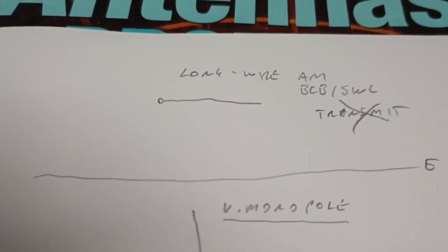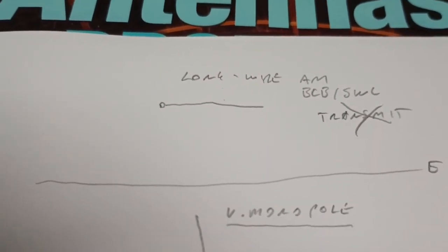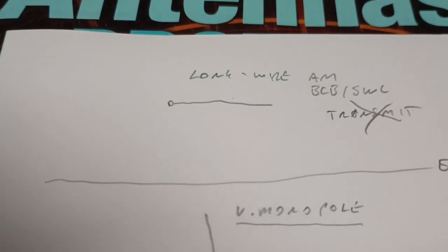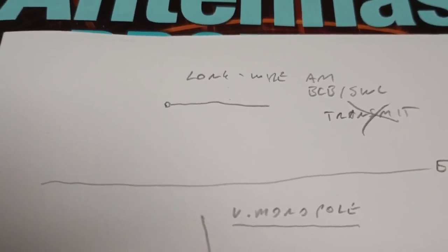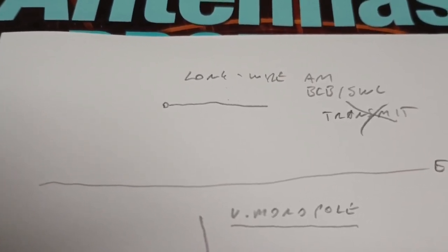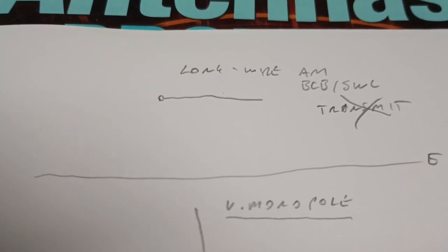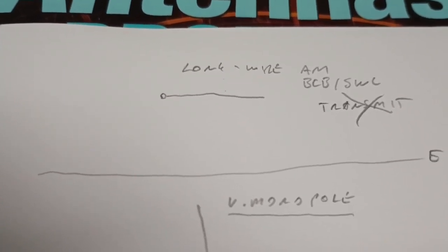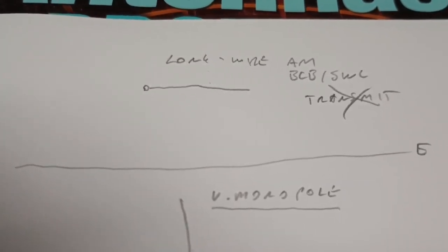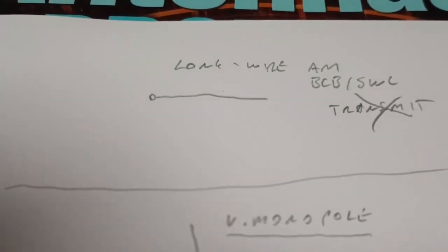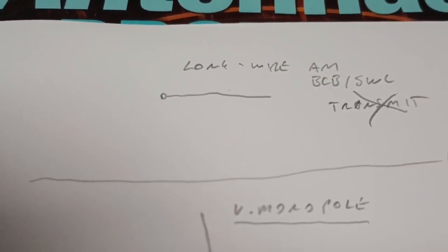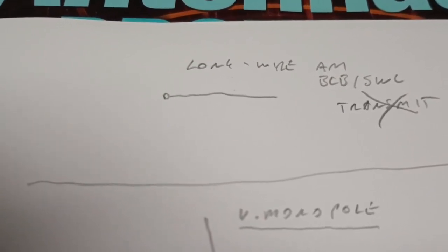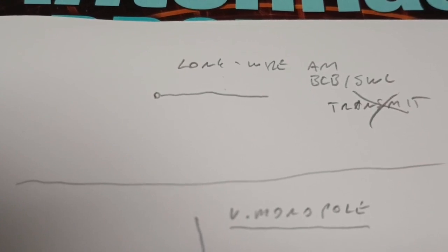The old Radio Antenna Handbook published by Radio Magazine in 1936 says the input resistance of a long wire can be about 2,500 ohms. Do the reflection coefficient calculation for 50 ohm versus 2,500. Calculate the SWR. It's basically infinity. That's why long wires don't work, and no combination of kludged up baluns or ununs or other ferrite crap is going to fix that because the wire hasn't changed.